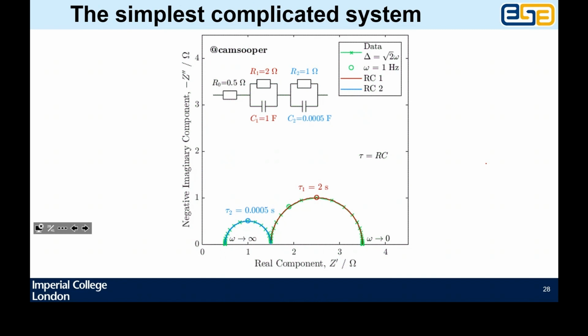If you try and do it more slowly, the reactance shoots off to negative infinity, and that's because you're moving it through and it gets full and is pushing back really hard, and you come back this way, it gets full this way, and it's pushing back really hard. So capacitors turn into wires, or can be thought of as just a wire at a high enough frequency, and can be thought of as an open circuit at a low enough frequency.